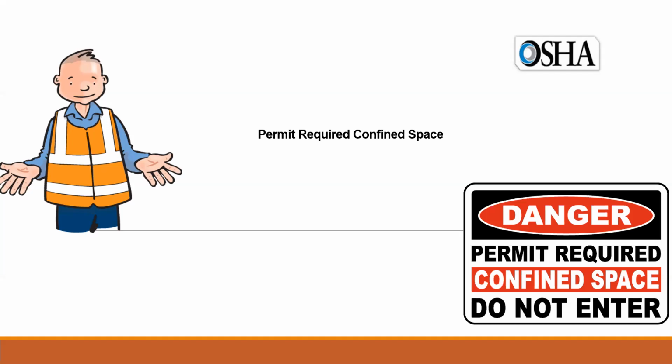A very good control about permit, I have seen in many companies, is that they link the permit with the invoice. For example, if they are using contractors for some activities, they say, okay, when you are bringing the invoice for the payment, also submit the closed permit. So it's a very good control. When the permit is going to be closed, it means your client or your operations department, whoever it is, they agree or are satisfied with your work, and then they close the permit. Otherwise, they will not close the work permit.